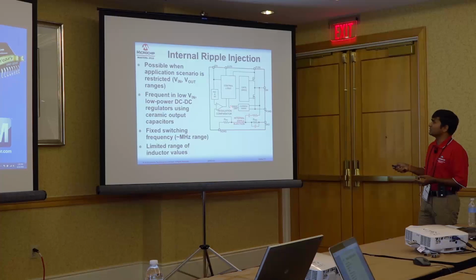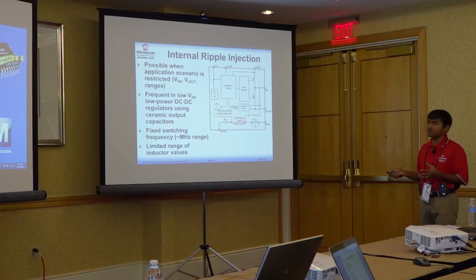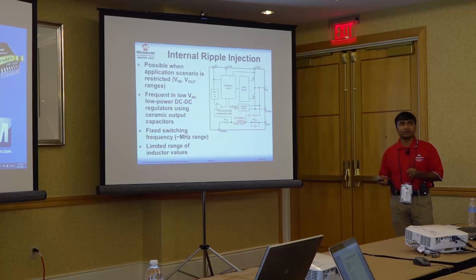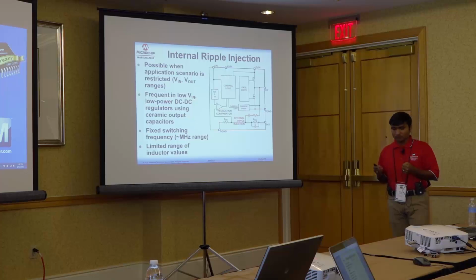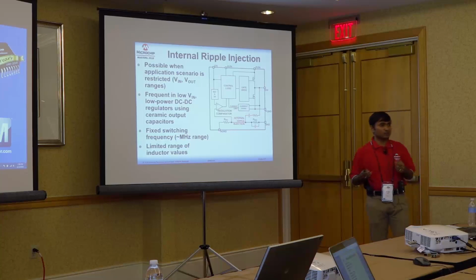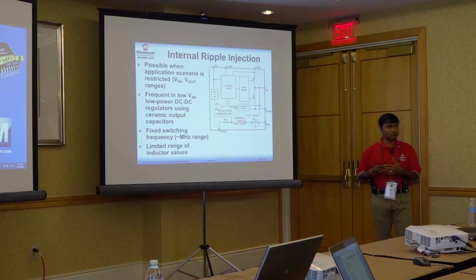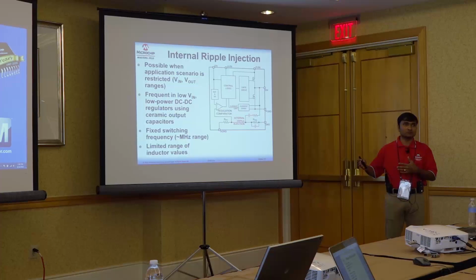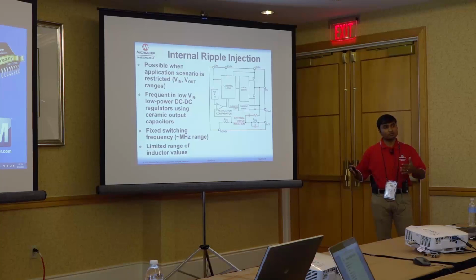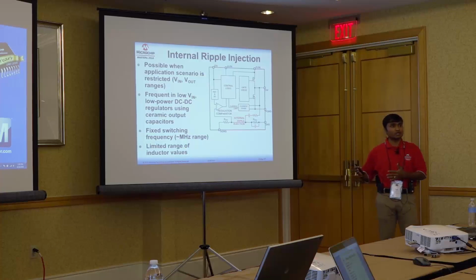So, this is usually available in low power DC-DC converter applications, but when we have a wide variation of the input voltage from 4.5 volts to 75 volts, which is the case with all of our COT controllers. There is a family of controllers from 4.5 volts to 75 volts, different generations of the controllers, and based on the controllers we also build integrated FET regulators.